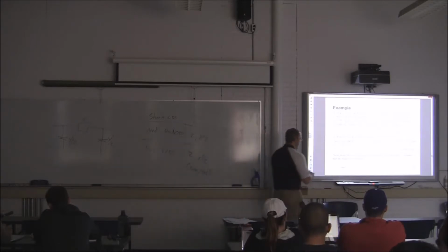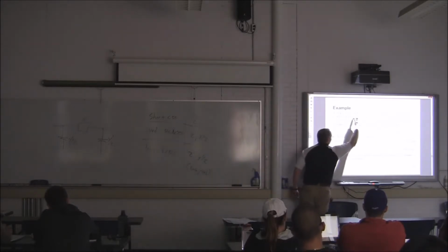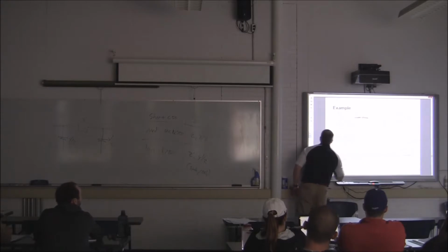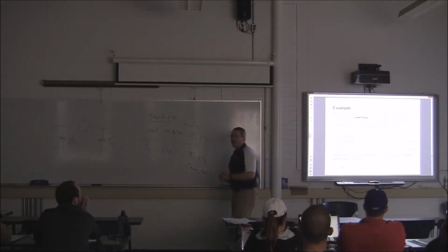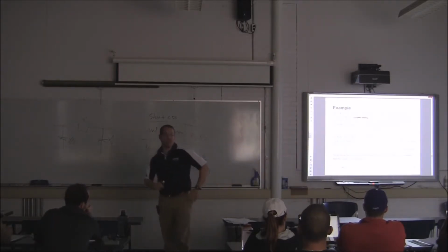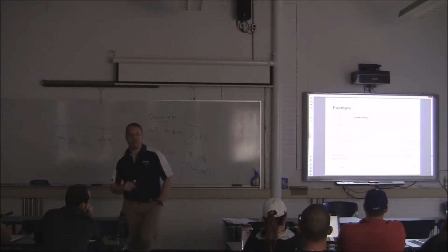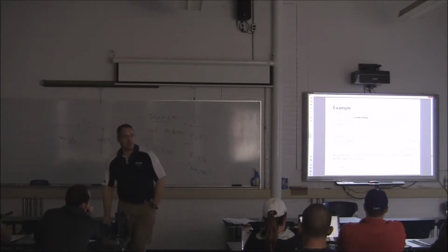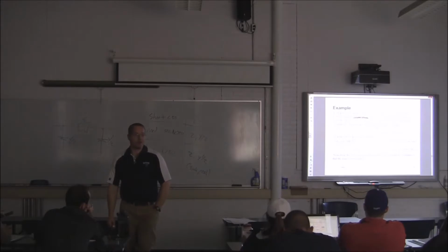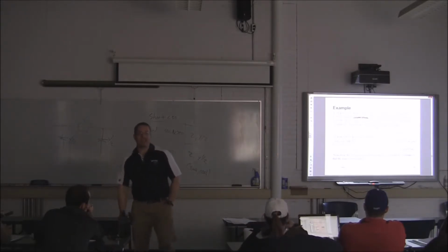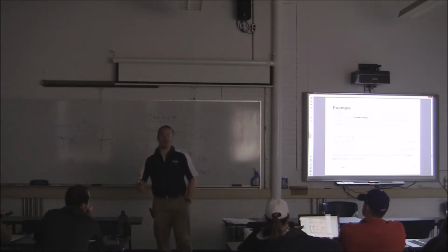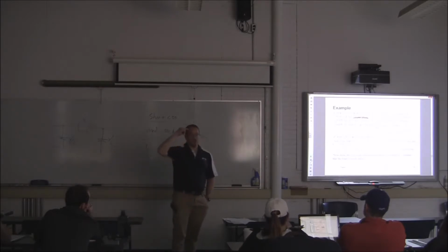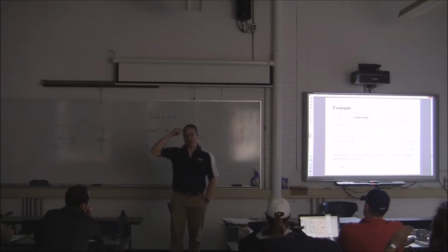Here's the key thing here. It's highlighted: all per phase. But remember, there's no such thing as a three-phase impedance. You should know that by default, or hopefully you will by the end of the semester. But that is a requirement. You cannot have a three-phase impedance. So this is something to think about and highlight in your notes. The bell should be going off saying, oh, these are per phase impedances.